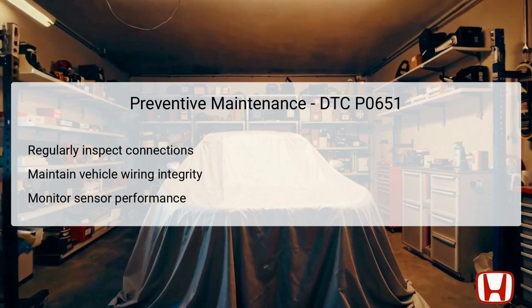Furthermore, regular checks of the sensors connected to the PCM can help detect performance drops or malfunctions early. Incorporating scheduled diagnostics using tools like the HDS can enable proactive identification of potential problems before they develop into faults. Ultimately, a commitment to maintenance will enhance the vehicle's reliability and longevity.